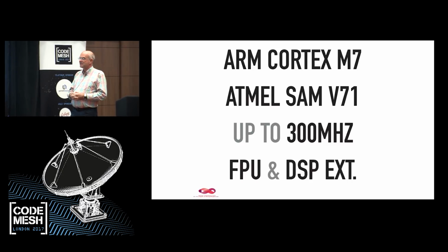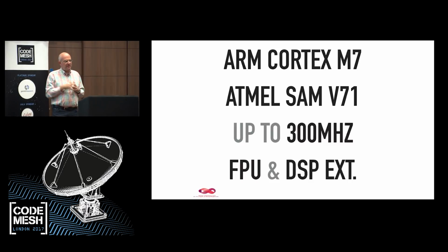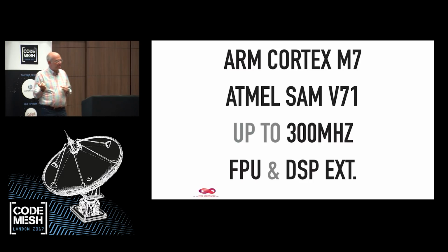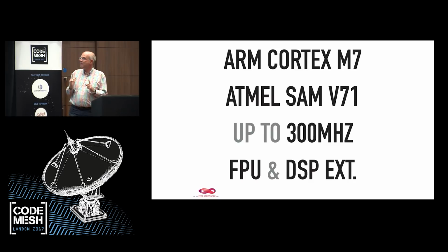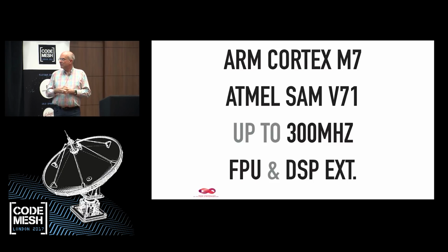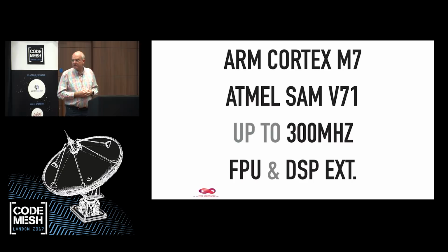It's an ARM Cortex M7, which is basically the M line of ARM is for mobile. For smaller things and less energy consuming things. M7 is the largest one of this line, if I remember correctly. There might be a newer one, but I don't know. So it's from Atmel. It can run up to 300 megahertz. You can run it slower if you want to conserve energy, of course.